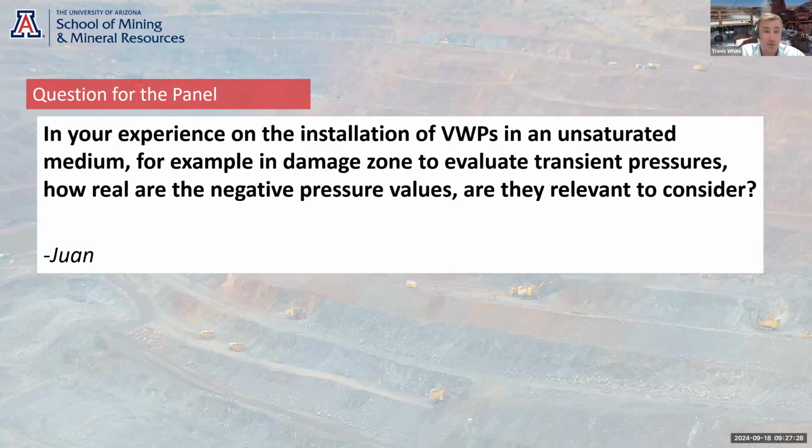Yeah, fully agree with Jeff. Just to add, we see it pretty commonly on tailings dams. You see these -1 meter, -2, up to -3 meter pressures, especially around the walls where you get a bit of drainage. It's very common there. So that is relevant, but beyond 3 meters, probably not right.